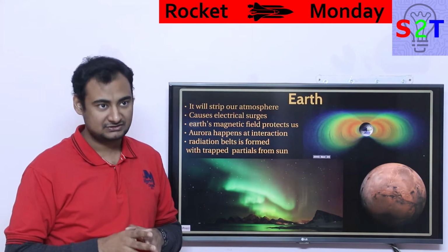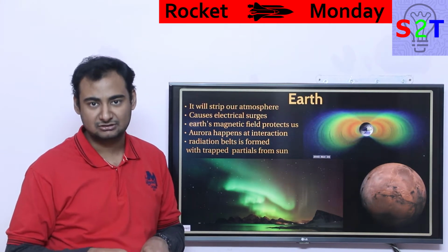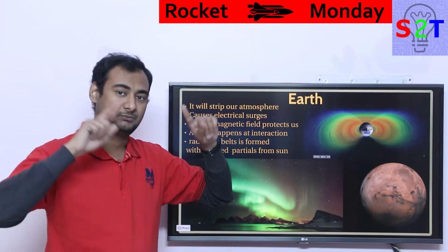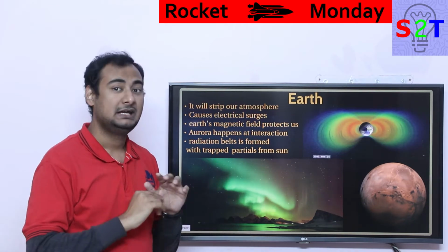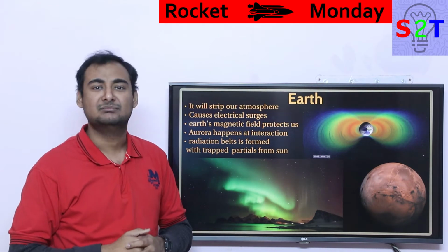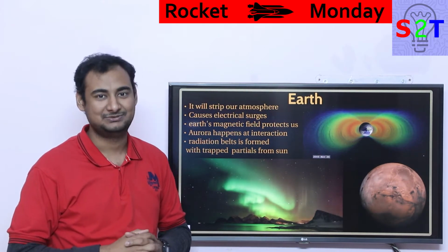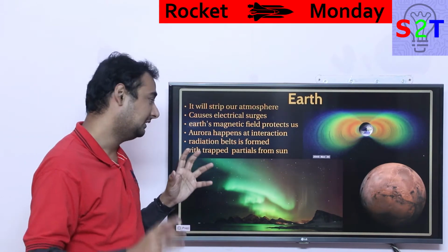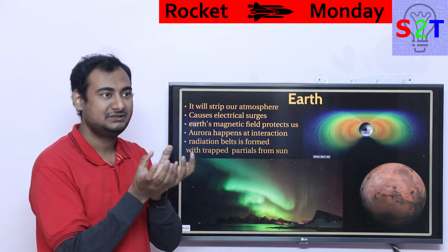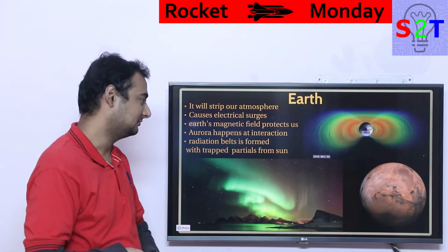So if you want to put your satellite up for long-term use, you will put it either in low Earth orbit, so it's protected from this, or much further outside of this, where it gets much lower radiation doses. And if you have to go through this, you'd better have multiple spare satellites. And now you know why GPS has so many spare satellites. So that's the whole thing you have to understand. That donut trapping is really awkward for us to deal with.